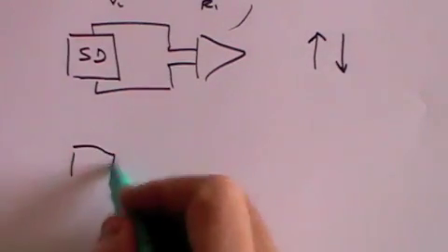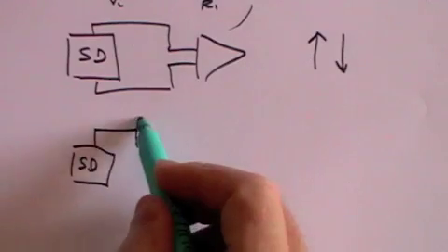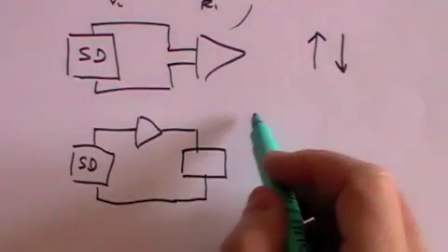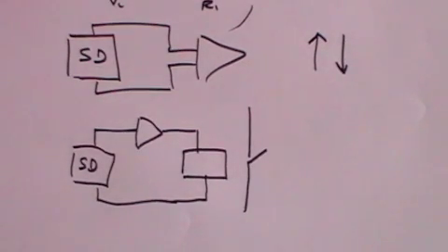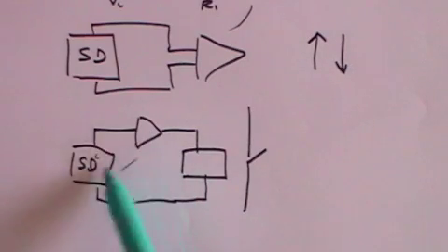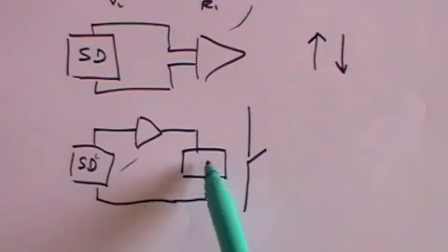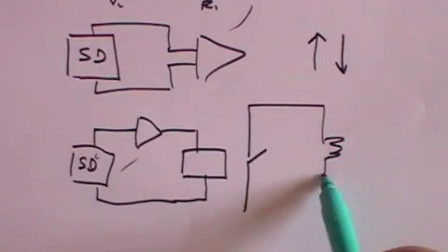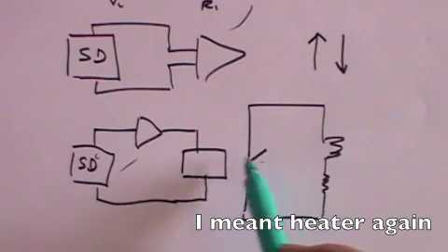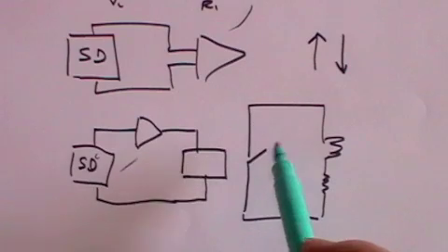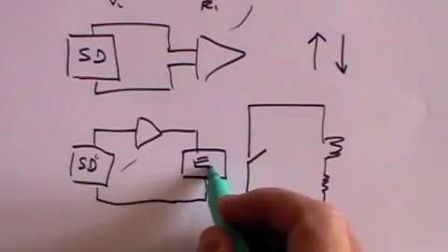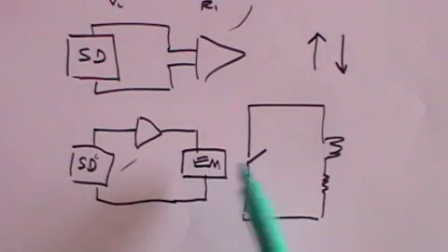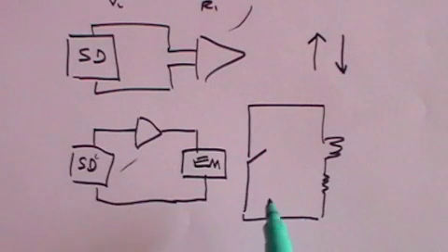What that means is that the circuit of which the sensing device and indeed the operational amplifier is a part will come to some kind of device here that will cause a switch over here to switch on. So somehow the action of the sensing device and the operational amplifier will cause this, whatever this is, to make that switch close. And that switch, of course, could then switch on a light or a thermostat or anything you like. And that process whereby a change here causes that switch to close is called a relay. And the best thing to use for that is an electromagnet, something which will not be magnetized until a current flows through it. But when a current flows, this becomes magnetized and causes the switch to close.